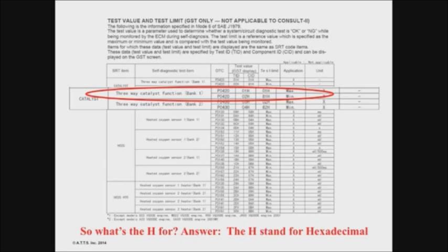Now this is all the Mode 6 data for this manufacturer on that car. There's not another drop. Catalyst, O2, O2 heater, that's it. There's nothing else. There's not another page. That's it for this year car back then. Nowadays, we get a bunch of information, correct? So it's all real important stuff. Now, here's another screen.